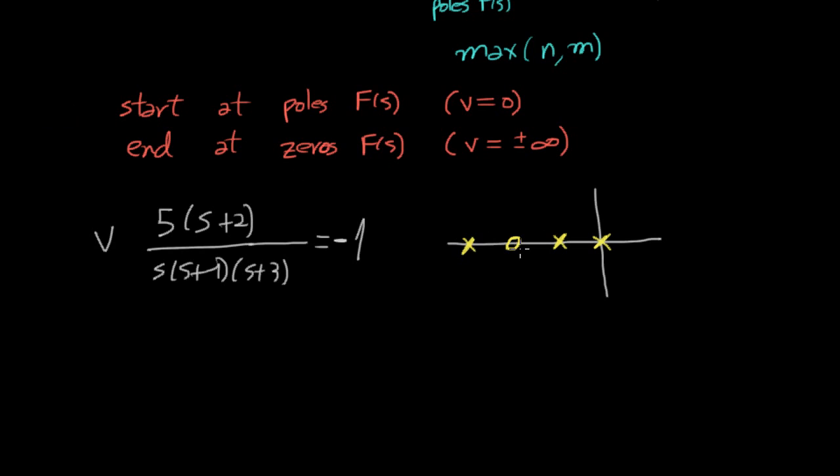The positive root locus has 3 branches. One of them begins here and ends in the zero. And here we have one branch that tends to infinity following a certain asymptote, and this other branch tends to infinity following another asymptote. So another way to see that is that they end in the other two zeros of this function, which are at infinity.